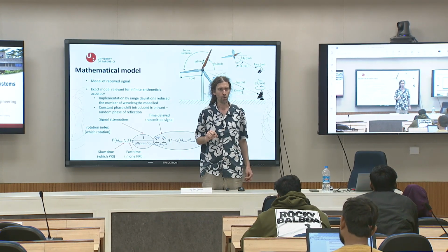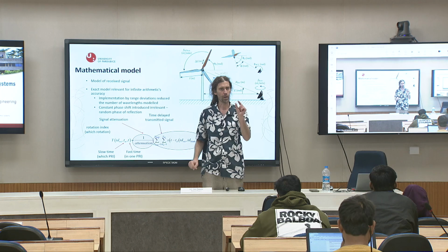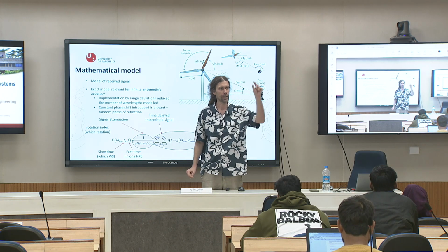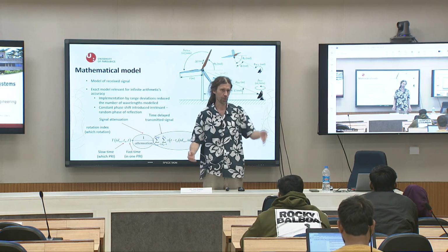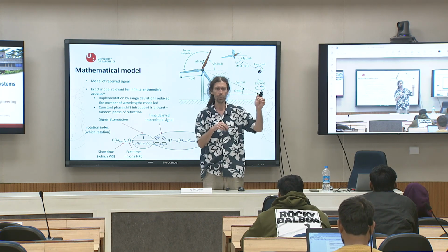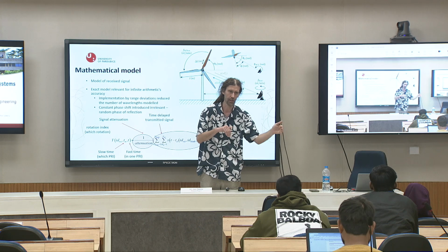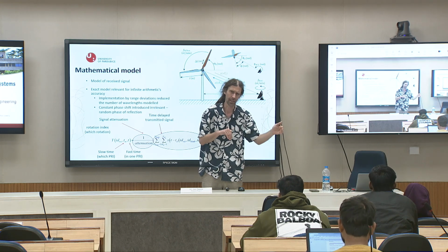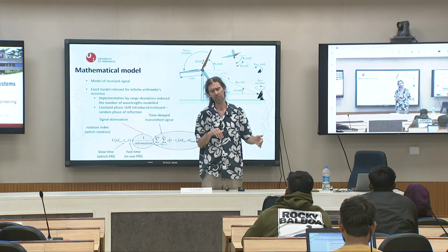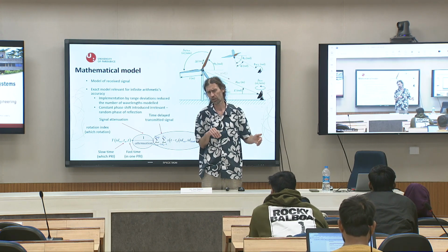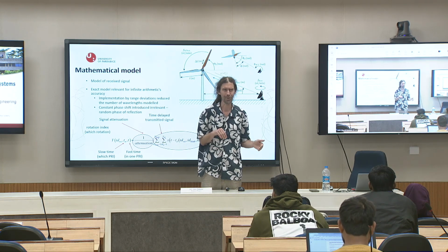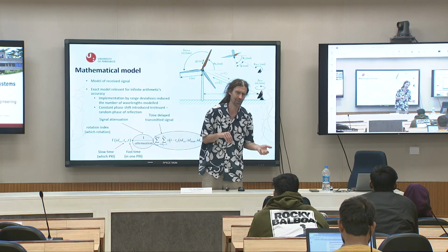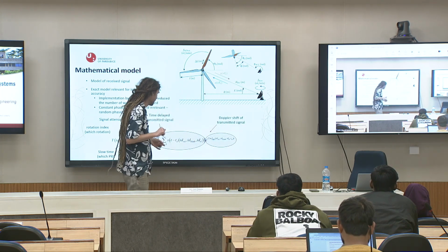You can choose only blade elements of one size, and each blade has the same number of elements. It would be so complicated if one blade has, I don't know, 5 elements and the second 50. It is not necessary. And honestly, the produced outputs will be weird. It will be odd, because one blade will be simulated with higher resolution than the second one. I think that is not necessary. I think that is clear.